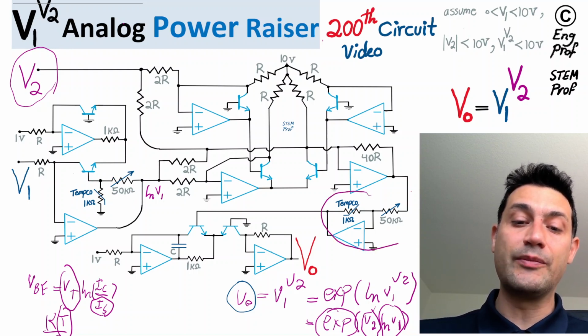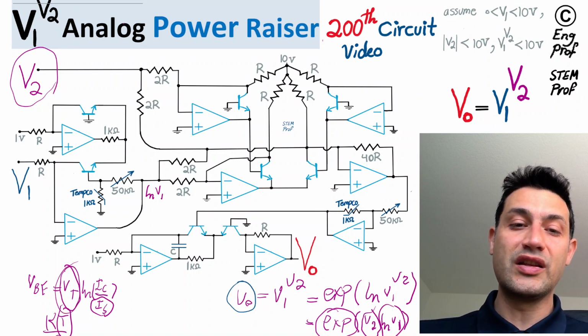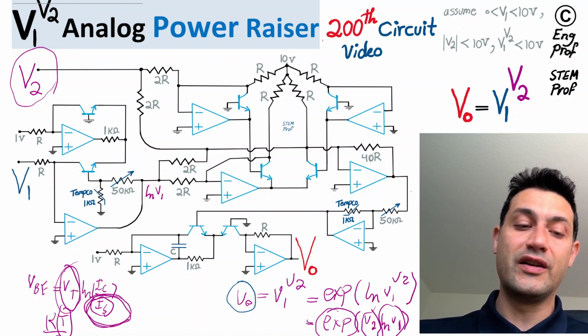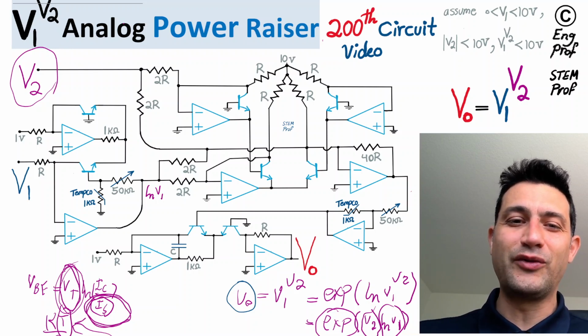The same here, this TEMCO or temperature compensating resistor, combined with this 50K potentiometer, which I'm going to zoom into 40K range, is going to help us get rid of again the dependency on VT as well. So in the sub-circuits, we not only get rid of the very varying and temperature dependent IS or saturation current, and we also try to remove the effect of temperature dependency because of VT to a large extent. So that's the big picture. I hope that at least this conversation is helpful before we get into quick details of computation.